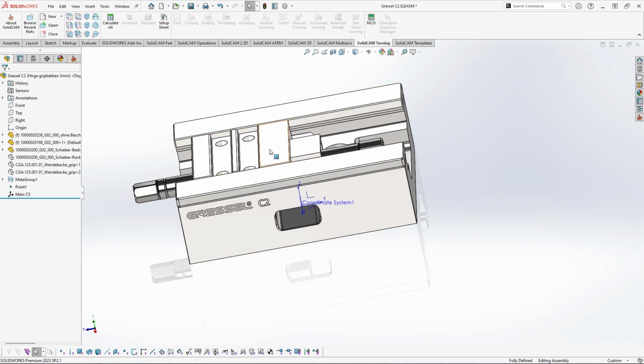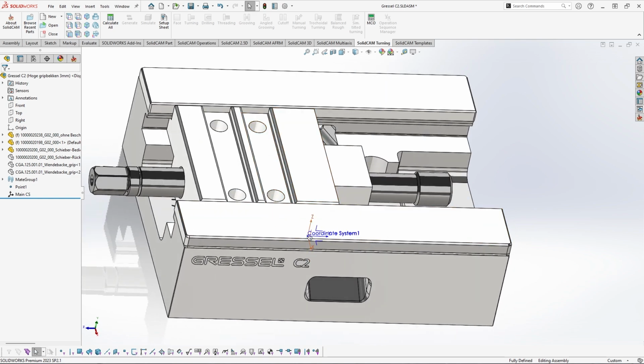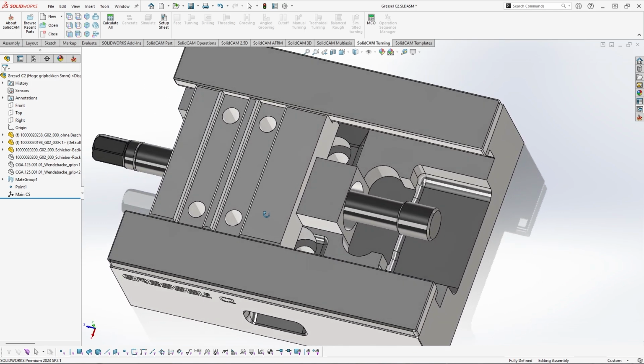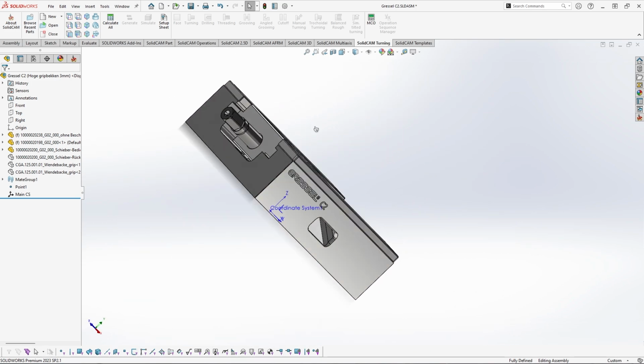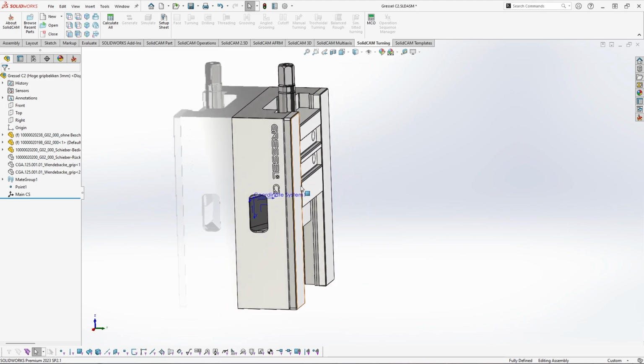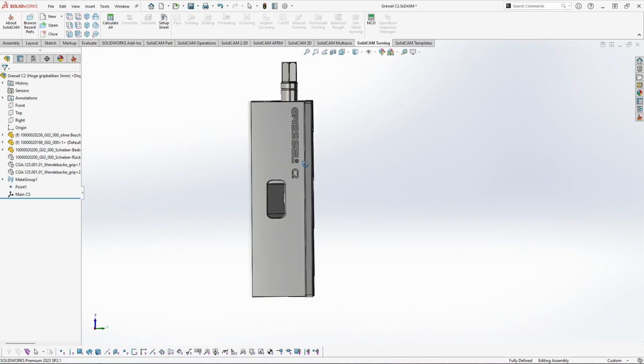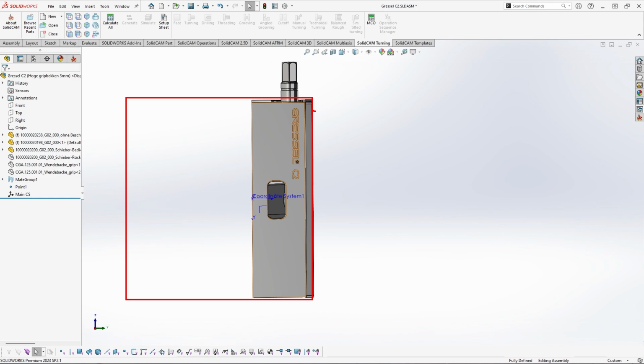Right. The next one, I'm going to unhide it. It will be this linear joint. I can place this coordinate system anywhere, or I can use this one for the reference. But in cases when you want to use the AutoClose function inside SolidCAM, which I'm going to show you later once we test this fixture, AutoClose allows you to automatically close on the target. This function works only if you look at your vise or fixture like a chuck jaw system. So basically, you can imagine this as a chuck, and then you have your jaw. I'm not very creative here, but you understand what I want.